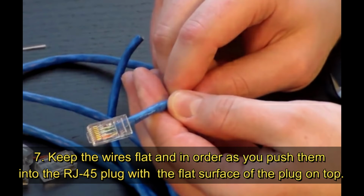You may have to use a little effort to push the pairs firmly into the plug. The cabling jacket should also enter the rear of the jack about 1/4 inch to help secure the cable once the plug is crimped. You may need to stretch the sleeve to the proper length. And don't forget to verify the sequence if it is still correct before crimping.